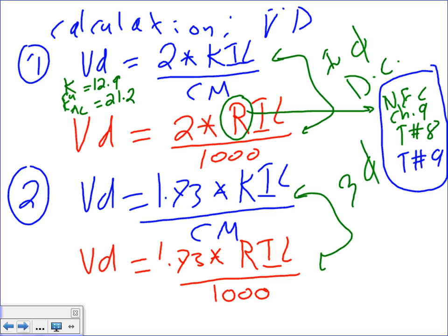I don't understand why then you wouldn't just use the one that's always got the constant, so that you don't have to go and convert to different resistances. Good point. What if the temperature is different though? That's a key point that I always use a table, guys, because the code is set. I don't want to worry about is this 12.9 or 12.1, because that 12 is temperature dependent.